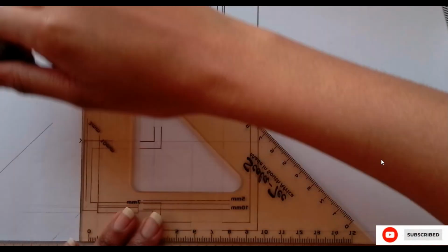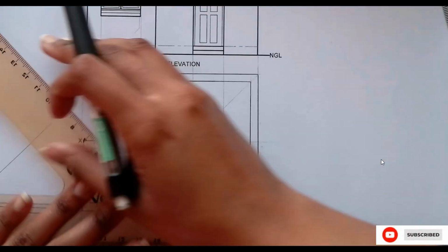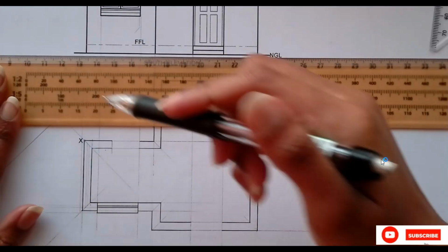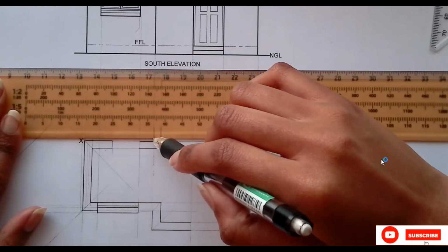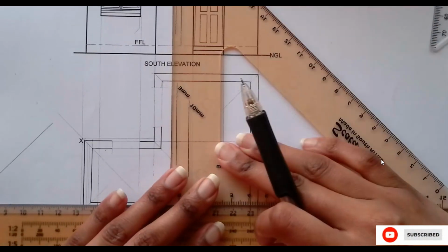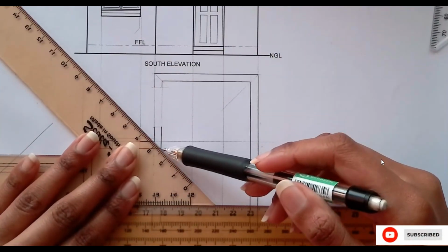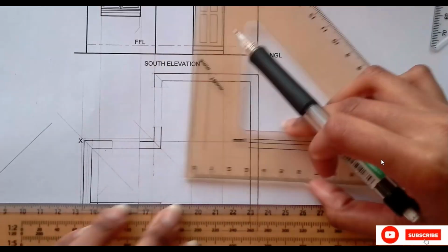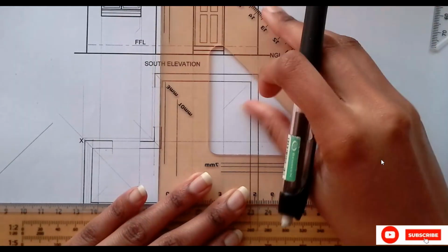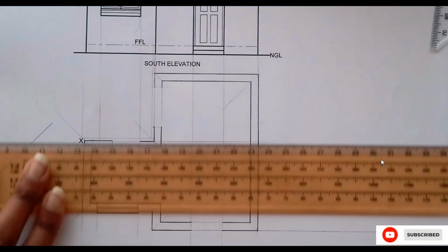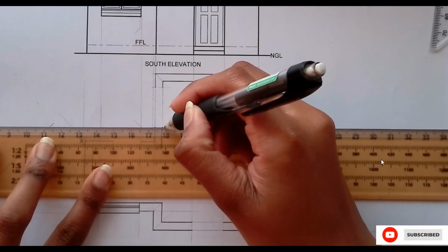So remember what you're projecting to that side. So what's going to get you the window and projection, just extending on 45. Coming on here. Let me extend this 45-degree line. Where it touches it, I'm going to have a line for my window sill. Then immediately I can outline the window sill.